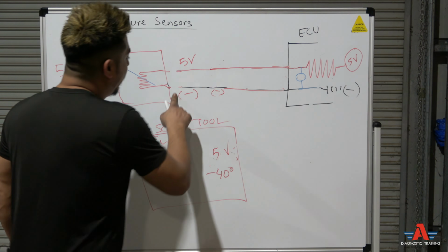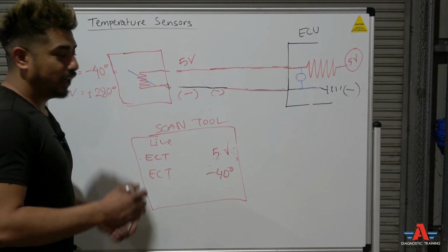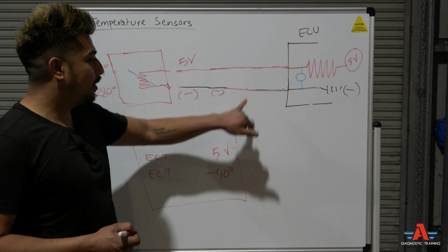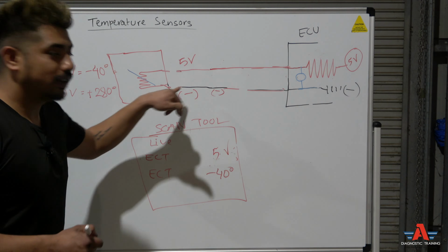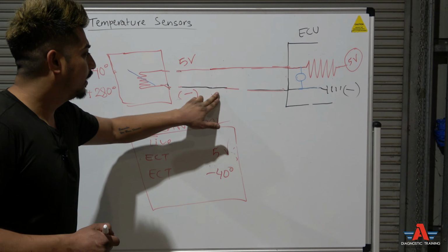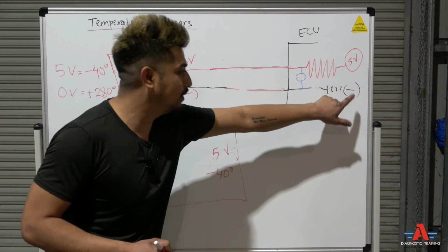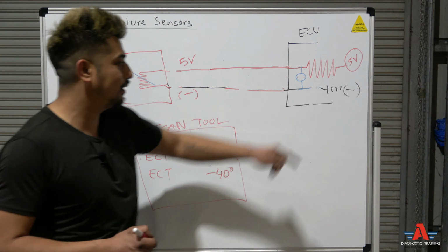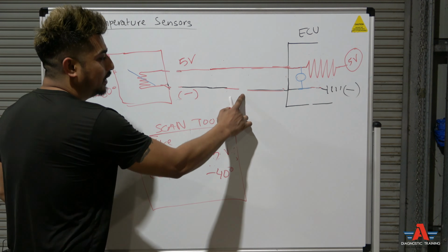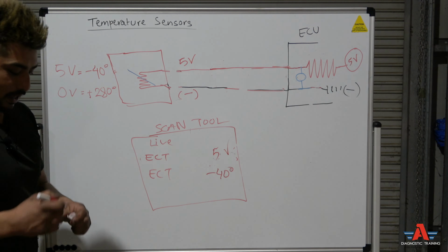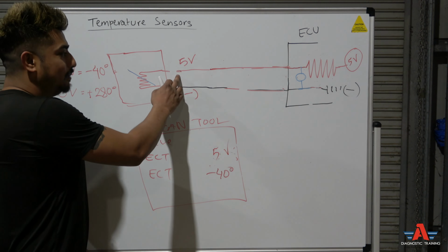You disconnect the wire, and nothing changed. There could be a possibility that you've got a break in the wire on the earth circuit. Or you could have a problem inside the computer; this circuit could be burnt inside the computer. Let's say for this example we've got a break in the earth wire. Does it matter?